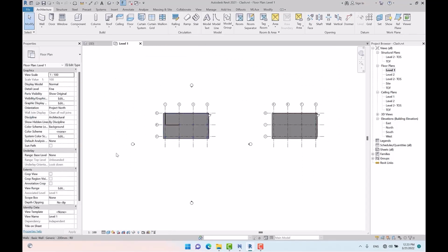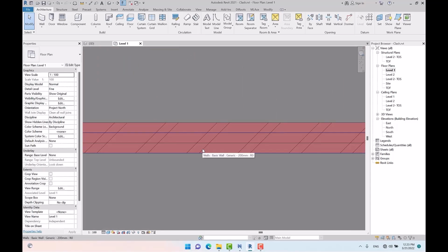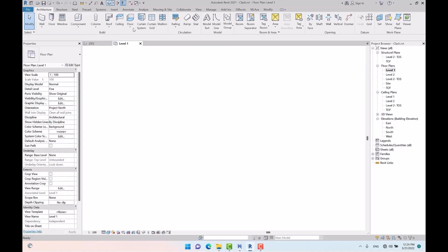Then in the other geometry we got no duplicates. For example, here one of the walls is placed inside the other one, and here there is an intersection in the thickness of the wall, and on the other side there are some longitudinal intersections. There are some parts which have longitudinal intersections. Here at the beginning of the video, I'm gonna explain the types of clashes. We will talk about the clash detection later. Here we're just gonna talk about the clashes that can occur in the construction process. At first we should get familiar with the clash detection system of Navis, and then we will move on and go through clash detection topics, and I will explain everything.